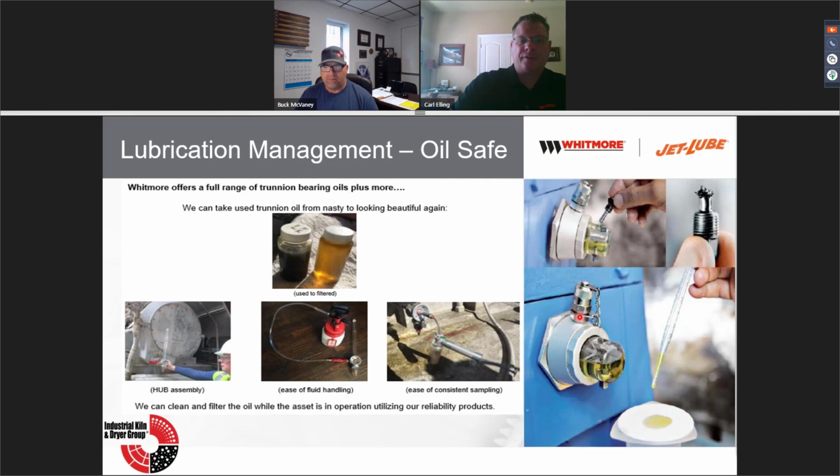A lot of times, if you're not doing oil sampling from the same point or lubricant point, and you've got different people taking samples, they will all go in different spots to take samples. This helps eliminate that because you've got the one port to pull from. So it's a really good practice, and it's starting to be standardized more and more. And here's a picture of the magnet and what it picked up as far as metal shavings. And that's this little thing right here that's floating in the oil.